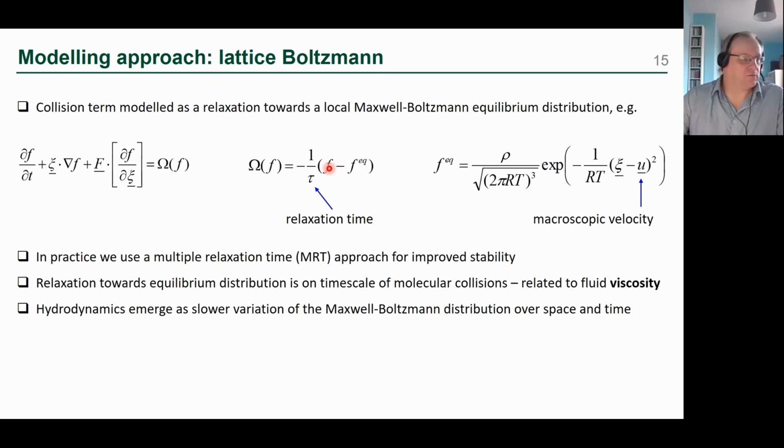On each time step, the particle distribution functions are relaxing to equilibrium, and the equilibrium evolves as well, because remember that the velocity and the density are calculated from the f's and fed back into these equilibrium distributions. You can think of the relaxation of the distribution functions as being on a time scale related to molecular collisions, i.e. a time scale related to the fluid viscosity, and then the hydrodynamics emerges as this equilibrium changes over time.